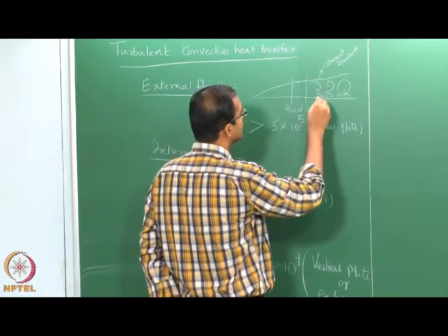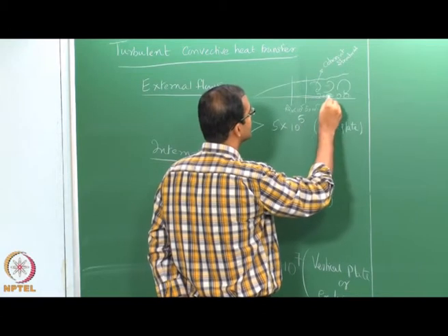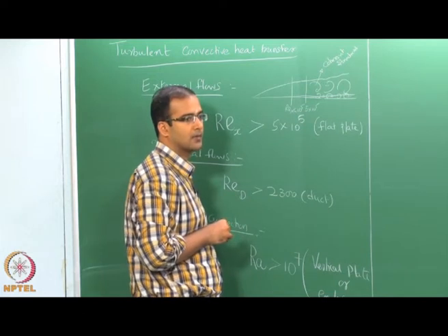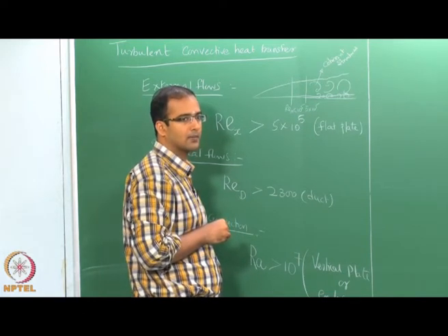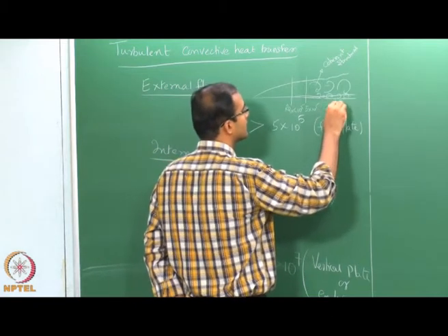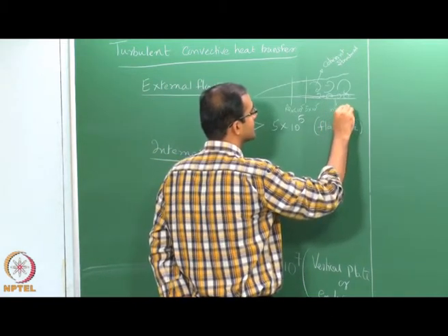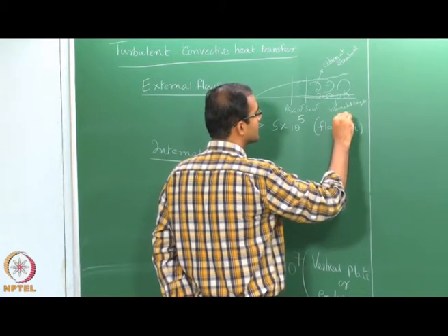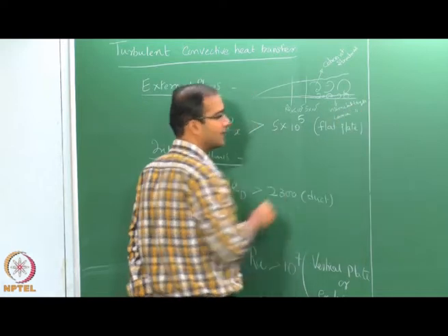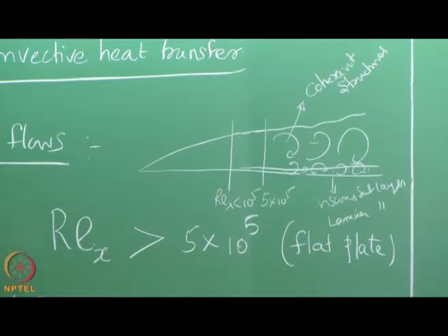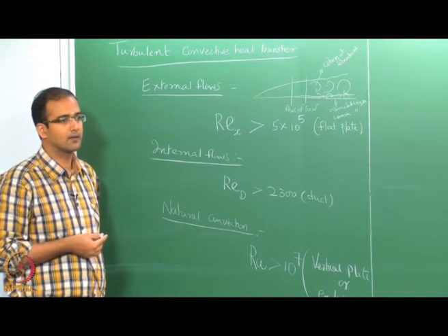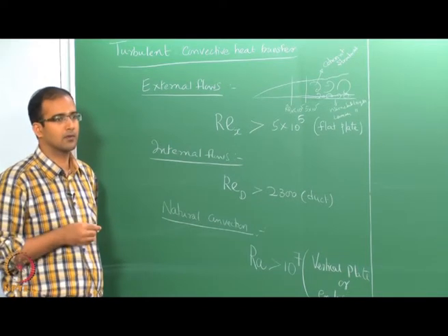So, essentially near the wall you have the effect of viscosity, which is molecular viscosity, which is predominant as compared to the turbulent motion, and therefore this will be referred to as the viscous sublayer or laminar sublayer, okay. Now the action of the wall therefore is to damp the effect of turbulence. Without the confinement, without the wall, you do not have a laminar sublayer, and you only have a range of scales in turbulent flow.